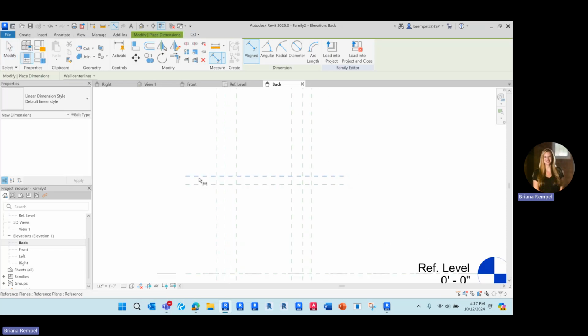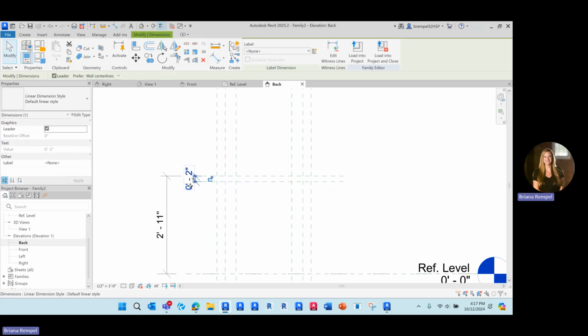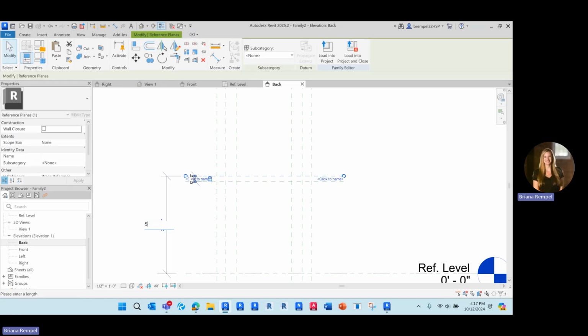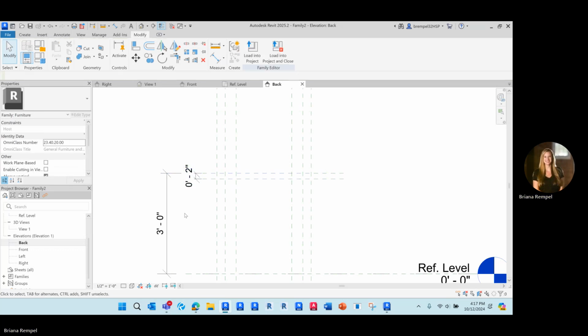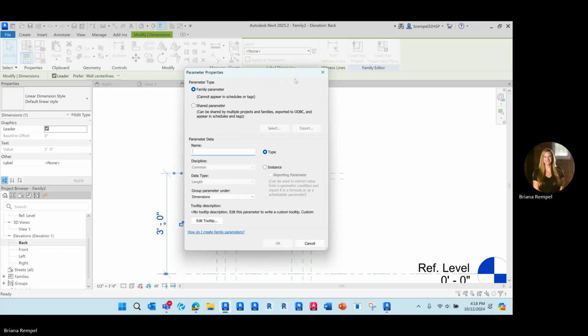I'm going to lock that one. We're going to do tabletop height, and then this one here, I'll put it at 2 inches. I'm going to lock that. So that means whenever this one moves, that one will also move with it. All right, so I'm setting that as a constant. If you want to be able to change that, that's fine. You can set that to another parameter.